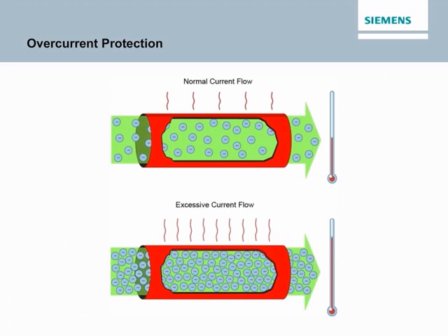Overcurrent protection devices are used to protect conductors from excessive current flow. Some overcurrent protection devices only provide protection in the event of a short circuit. Some provide both short circuit and overload protection, and some devices provide protection in the event of any of the three overcurrent types. Circuit protection would be unnecessary if overcurrents could be eliminated. Unfortunately, overcurrents do occur, and when an overcurrent occurs, a protection device must automatically disconnect the electrical equipment from the voltage source. An overcurrent protection device must also be able to recognize the difference between a small overcurrent and a short circuit and respond in the proper way.